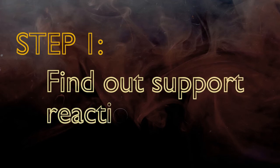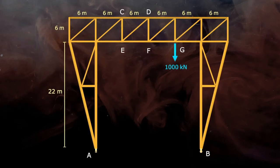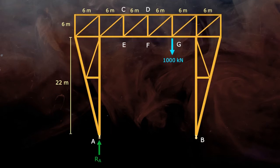The first step in this method is to find out support reactions. Here at joint A, there is a hinge support, so there will be two reactions, RA in vertical direction and HA in horizontal direction. At joint B, there is a roller support which restricts only vertical movement, so there will be only one reaction RB.